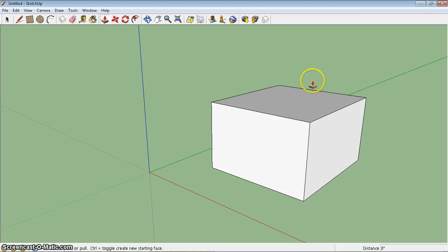Well, if I pull and I try to hover over that shape, it doesn't let me. Because once you create a component, that's the way it is. You've finalized it. So you want to get in the habit of not making components until you're pretty happy with that piece. Let's say, though, that you did make a mistake and you need to make a change.